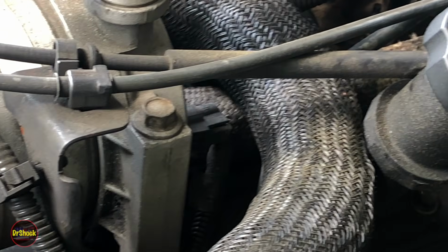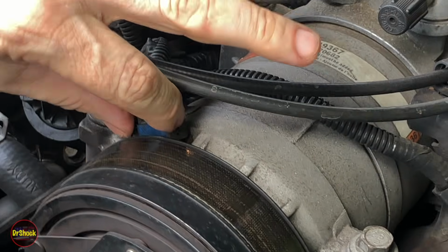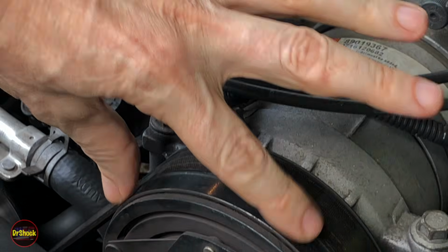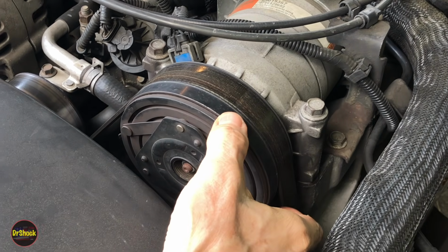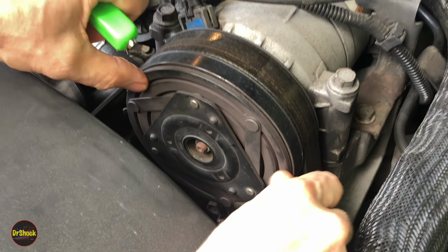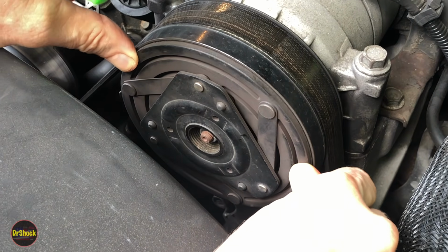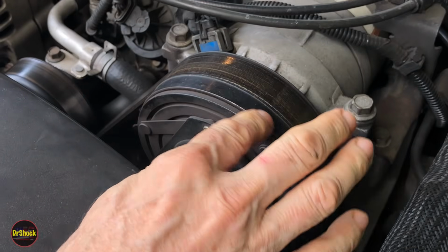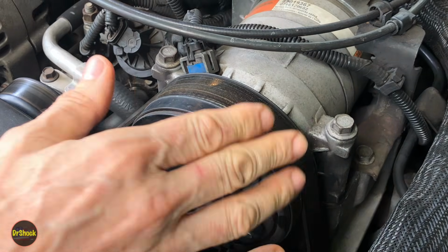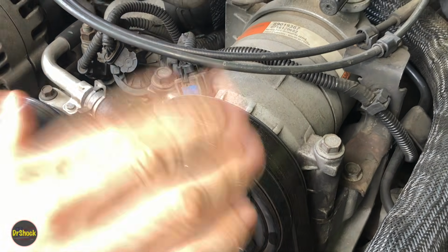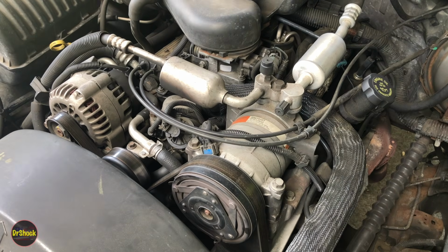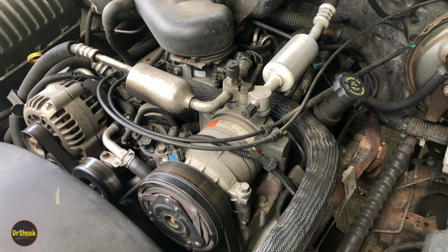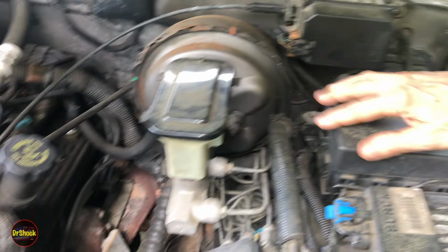And then the next is also on the compressor, in the front. This is the electrical connection for the electromagnet that operates the clutch. And then the last piece of this mystery will be the clutch itself. There's a plate here in the front that moves in when the magnet actuates it, and then the pulley surface on the front has a friction surface for that plate. So all of this is what we're going to be doing a process of elimination on, as well as the air conditioning relay that'll be located inside this box right here.